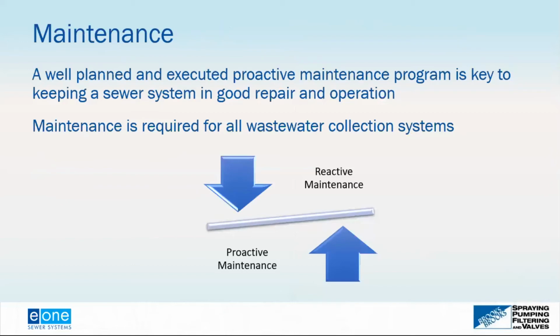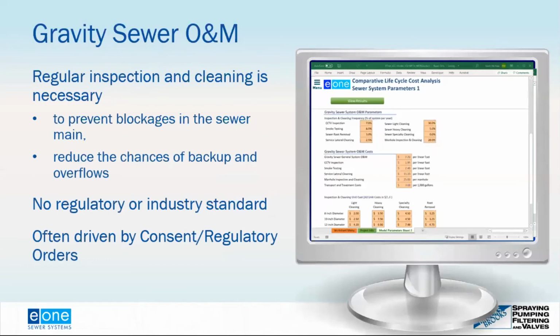Because it's really important to remember that a well-planned and executed proactive maintenance program is key to keeping a sewer system in good repair and operation. Maintenance is required for all wastewater collection systems. One of the things we hear a lot is that people say, well, with the gravity sewer system, I spend a lot more money up front, but I don't have to spend any operation and maintenance money. That's not true. There is regular inspection and cleaning necessary for a gravity sewer system. There's a huge industry of vac trucks, sewer lining, sewer cleaning. That's a lot of industry for something that doesn't have to be done.